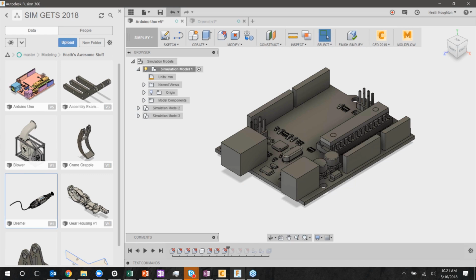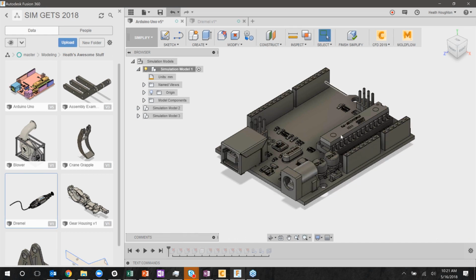Here's another thing that's really, really cool. Check this out. It's a timeline. So I can actually see my progress as I go through and make changes, and I can back up, insert new features. If I run the model, I find, oh, I forgot to do one thing, and I want to do it here, and then have my fluid created afterwards. Then we can start inserting new things.